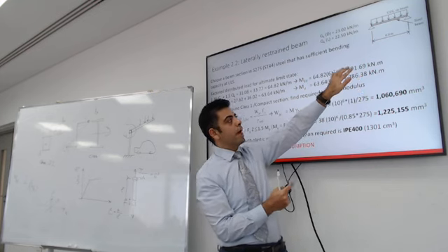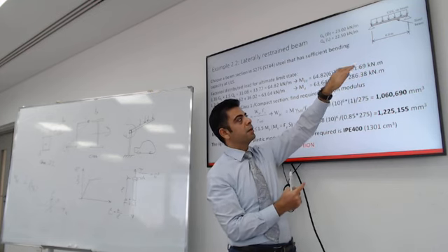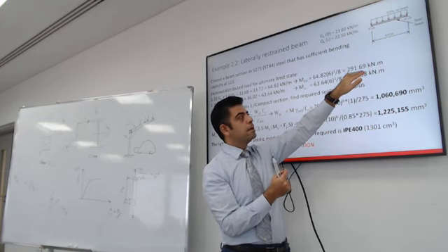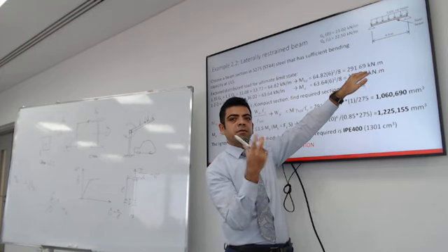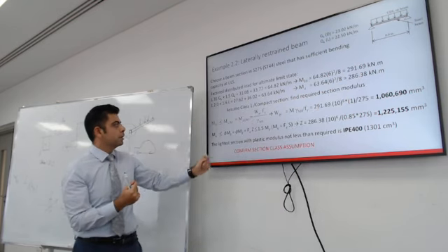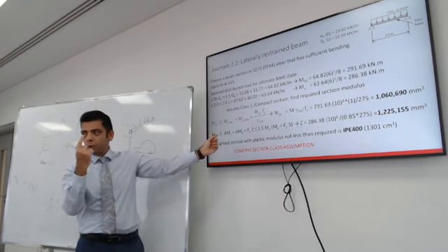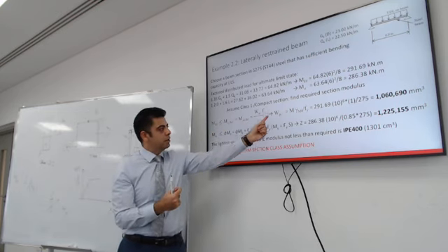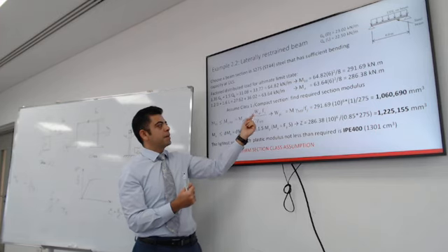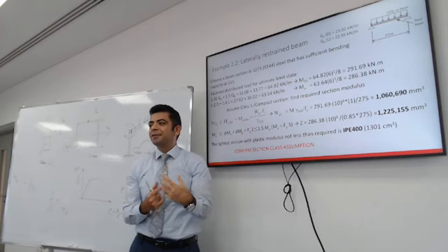Perfect. All right. So now this is the maximum moment under the Eurocode load combinations. So what is the section modulus strong enough to resist that load? I'm going to equate that equation to this moment to figure out the section modulus that is strong enough to resist that load.